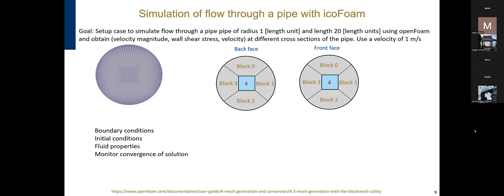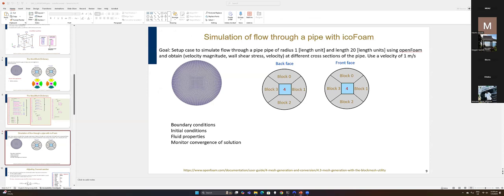So at the inlet, we are not going to define the pressure. The pressure gradient there should be zero. Zero gradient, yes. But then at the outlet, we are saying it's atmospheric. And if we are saying it is relative, then that would also be equal to 0. Anyway, we need to define the fluid properties as well, and you can find those in the constant directory.